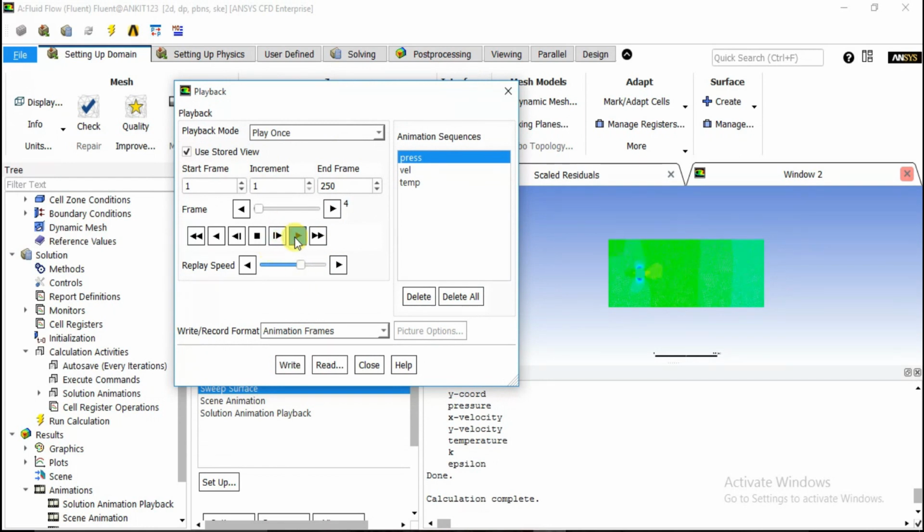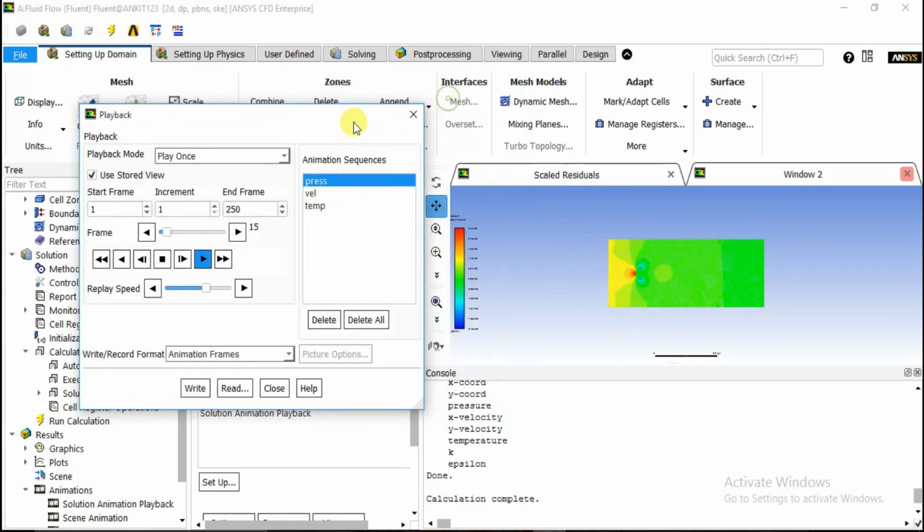So this is a contour of pressure variation. Okay, now you can see here the red region. Red indicates higher pressure. So basically this is the point where the fluid is coming to rest. Okay, you know what is a separation point, what is a stagnation point. So this is a stagnation point where the fluid is at rest, and whatever the loss of kinetic energy, it is basically converted to increase the pressure. Okay, and you can see here there is a formation of boundary layer. So in this region basically the pressure is low. Okay, and this green region is nothing but our cylinder.